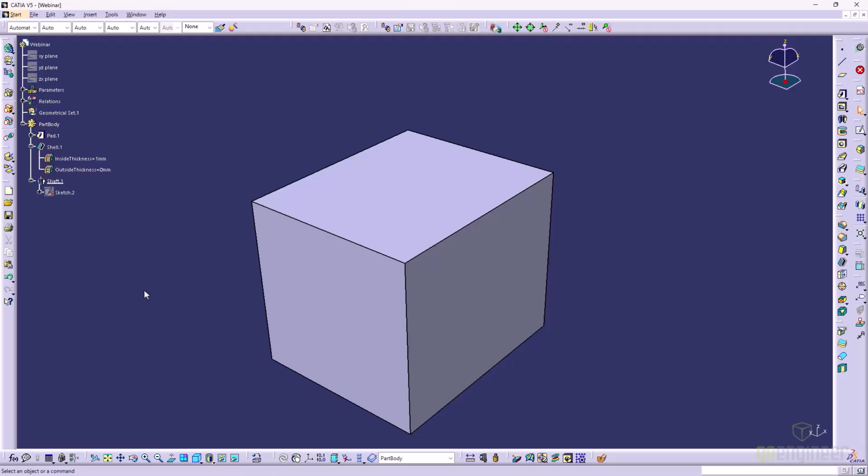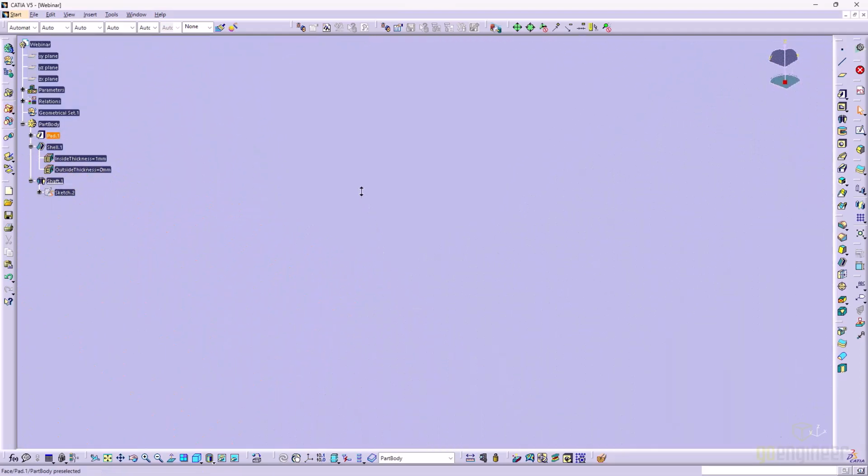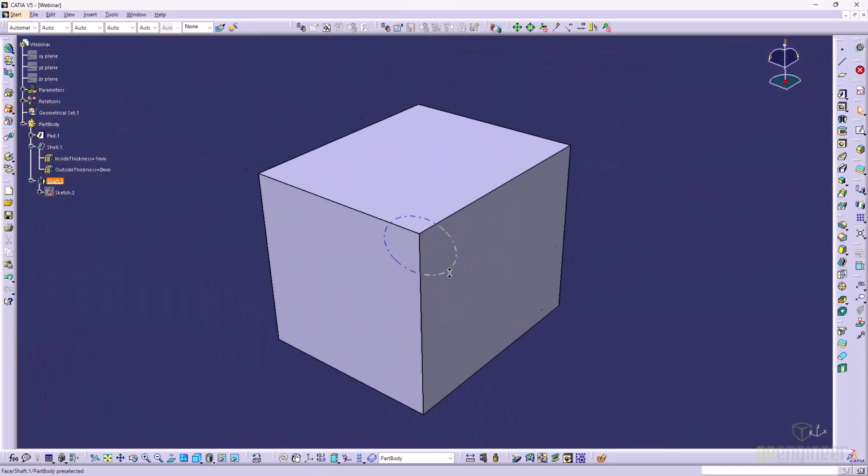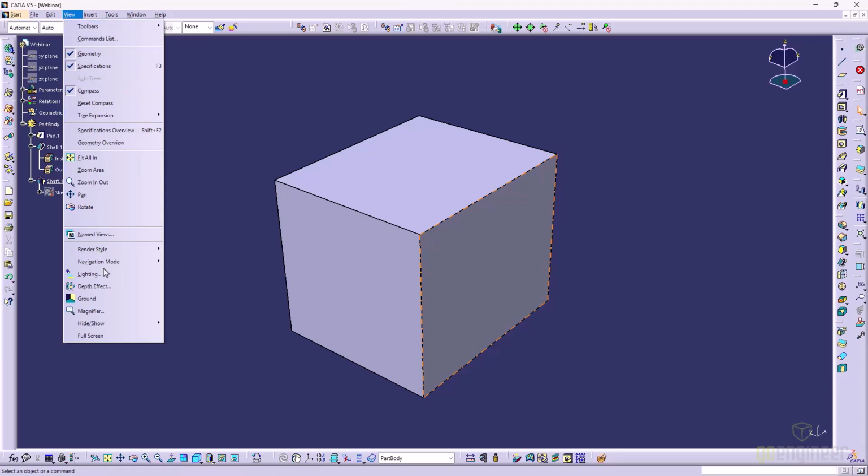Perspective view also changes how models zoom, moving the camera instead of the field of view, allowing you the ability to move between objects. This is helpful in large assemblies when you need to see how parts fit together. Simply switch modes and move between objects you would otherwise only see in section views.